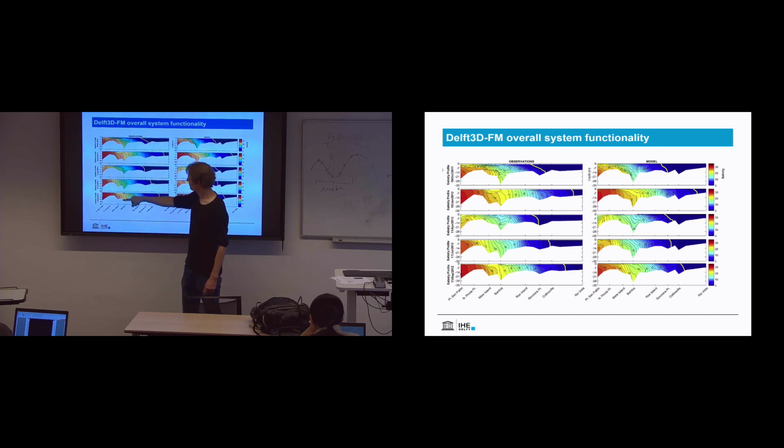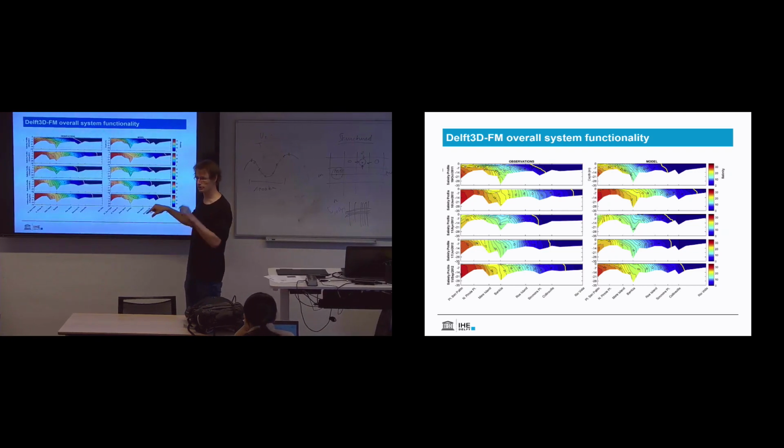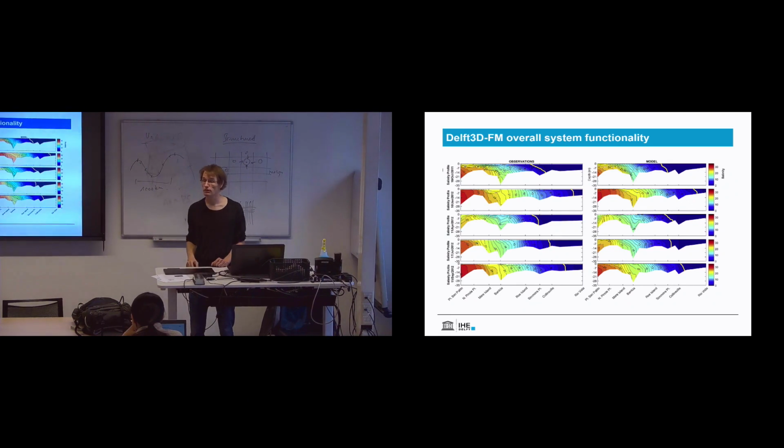And they did that a number of times, and then they made this really cool 3D flexible mesh model, of which you saw a bit earlier, a few slides back. And they tried to mimic this 3D behavior of salinity intrusion in the bay. And actually, if you match the two time steps with each other, they got really nice results. So this is actually a validation study with real observations of 3D salt dynamics in a very large system using flexible mesh.